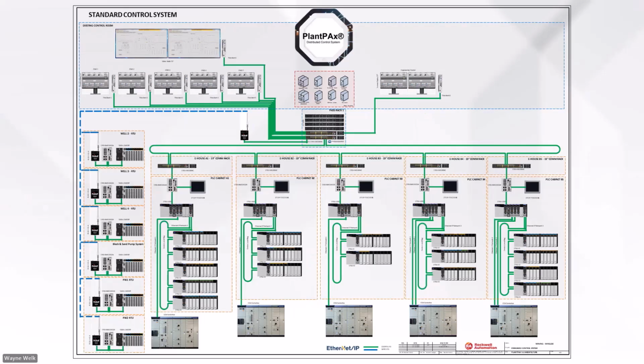So this is a little more detailed example, and this is an example of an MCC being connected directly, actually a couple of different examples there. If I look closely enough, there is a redundant network connection to a couple MCCs, and then a single network connection to the other. But it's all connected to the controller, and so all of that important actionable information from the MCC is going directly into the control system to provide value.